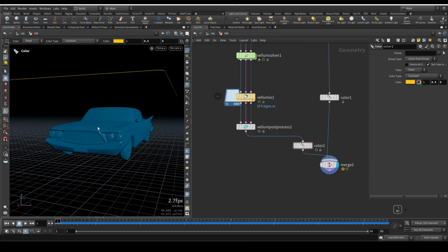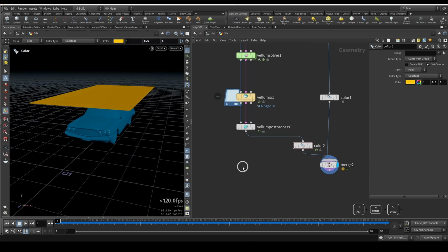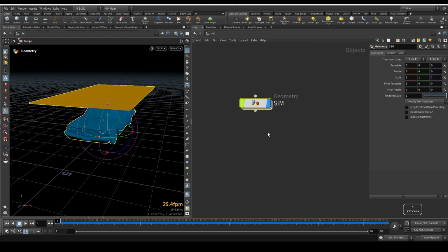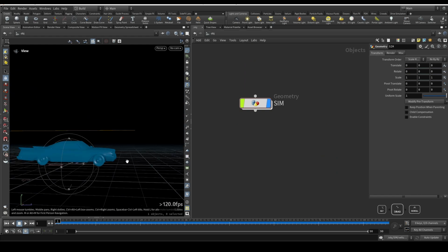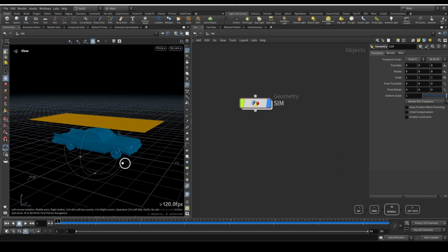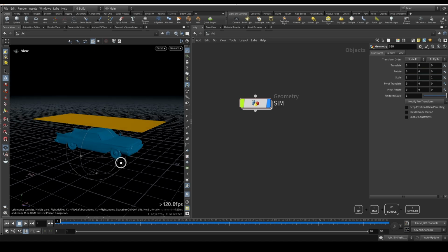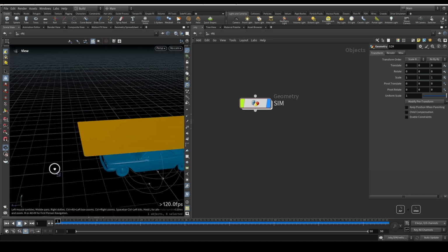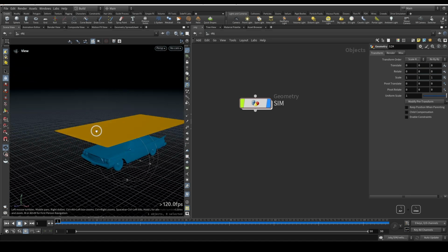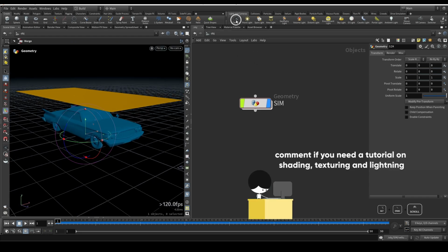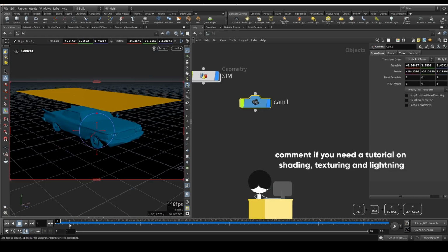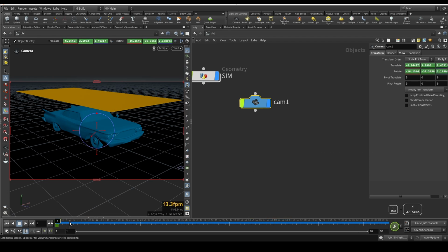Also, in case you want to add a camera to it, you can press U to jump out, select your framing, whichever you like. If you want a side view, a cross view, ortho, what do you call this? A perspective view. Let's select this, press Alt and left click to frame the camera. And if you want to add some animations, you just click on this keyframe.